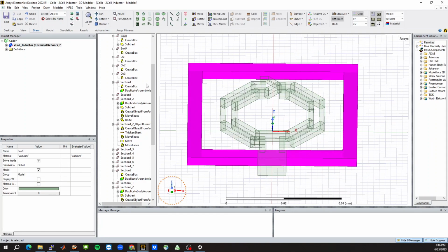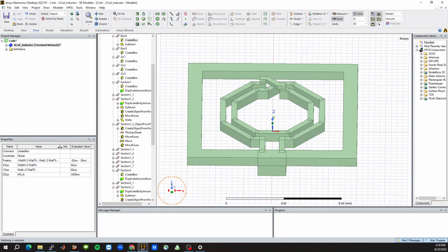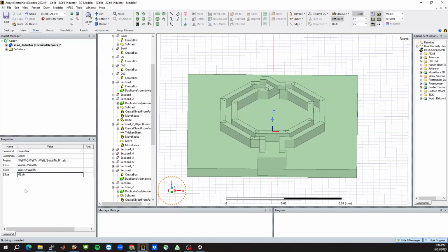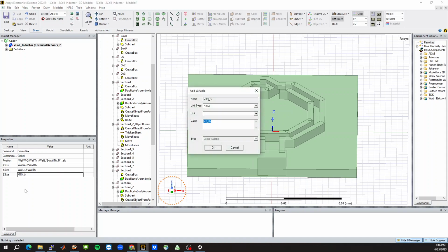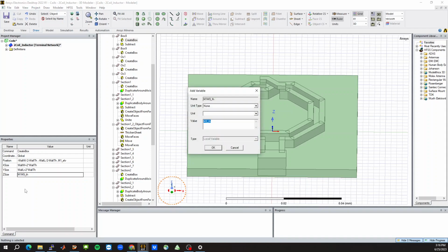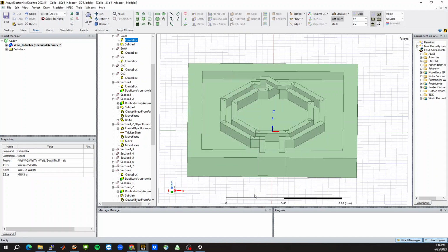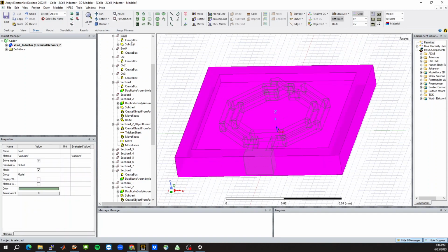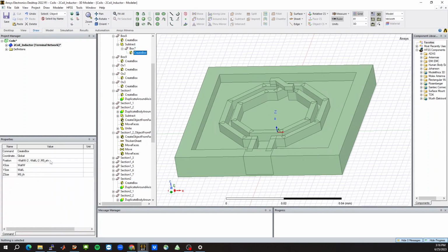Okay. The ground wall actually should be a bit different. So this should be M1 elevation, which is say 590 nanometers. And I want this to be M1, M9 thickness. I want the ground wall to be all the way from M1 to M9. So let's say the total thickness of this is 8185 nanometers. Okay, that looks like a wall. Of course, I also need to do that for the subtracted box inside it.